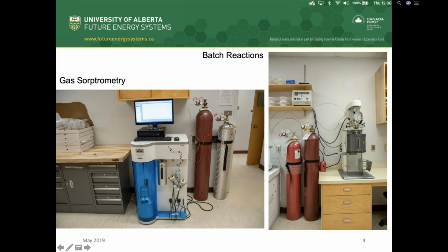So in this machine, we can do experiments based on the chemical reactivity of the reservoir itself. This is very important for production and injection testing, as well as reducing the risk of induced seismicity. And it can also do scaling and corrosion testing, which reduces the risks of mineral fouling in the surface plant. We're able to do a variety of different kinetic and equilibrium mineral solubility experiments in this reactor.